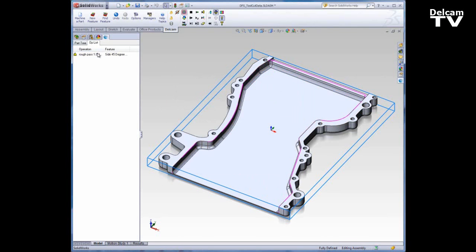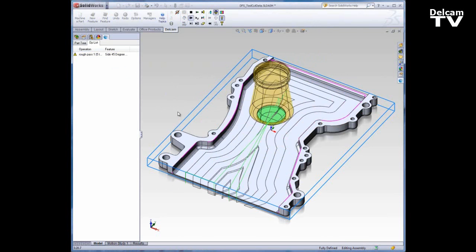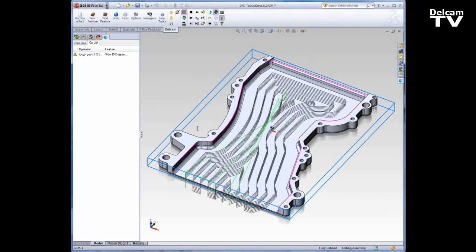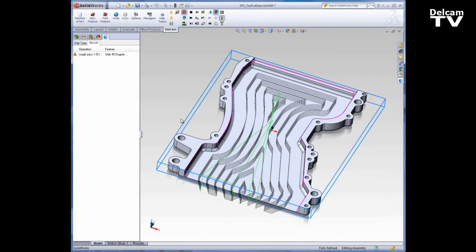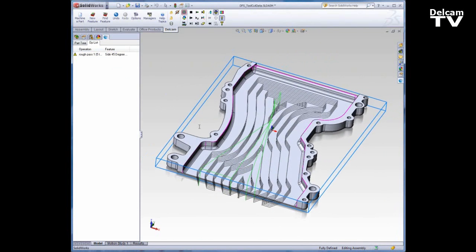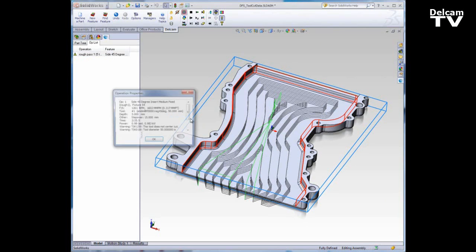And we'll check out this toolpath. Obviously more steps, and again, I didn't change anything but the tool, and a narrower step over. If I go again to the properties by double clicking the operation, it will show us that even 3 mm depth of cut. Of course, this was able to work out evenly because it's a 15 mm deep feature. And there's our 15 mm width of cut. So this worked exactly as expected.